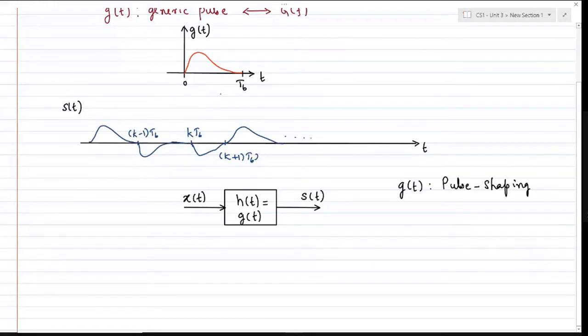I just don't want to kill time calculating the power spectrum for individual types of line coding schemes, because I can have any kind of scheme, as I told, the on duration could be 25% or 50% or 75% and so on. So I don't want to do it for individual line coding schemes. I want to come up with a generic mathematical structure to find the power spectral density in general, and I'll substitute according to which line coding scheme I'm talking about.